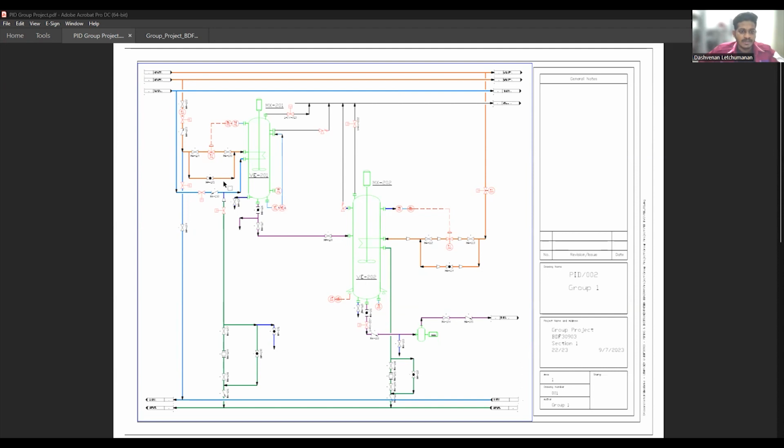The steam line has a bypass, which is required during maintenance. The bypass will be used during maintenance of the control valve or temperature valve at VE201. VE201 involves a feedback control loop system, where the control valve is controlled by the temperature indicator and temperature level indication from VE201. When it requires more temperature, the control valve will open more. When it requires less temperature, the control valve opens less.